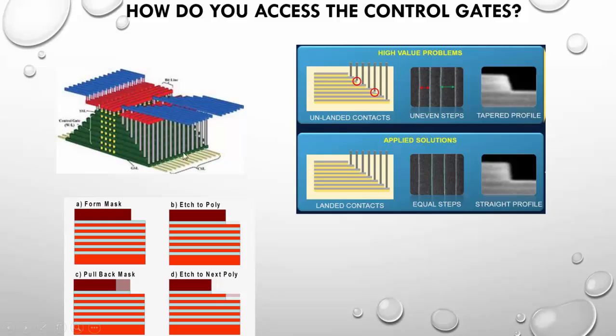You can see here a stair step pattern. I said that these connections are made by etching a stair step pattern into the layers and sinking wires down to connect with each layer. This is illustrated in this one, like in Samsung TCAT, or TCAT 3D NAND. So stair steps are difficult to manufacture, you know.